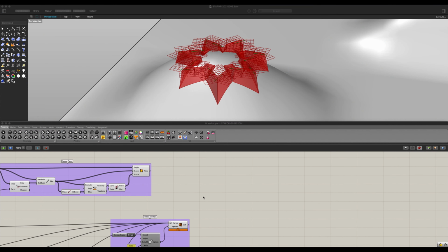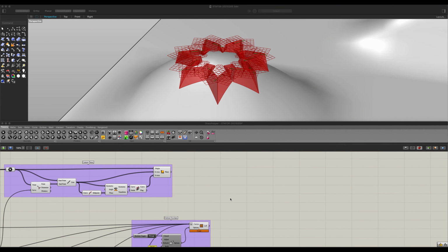Now we finally add in our cannons. And to start off, we want to get ourselves a Brep here. Let's copy and paste this component here, and also let's get ourselves a curve. Going into Rhino, let's select our curve as mentioned at the very beginning.